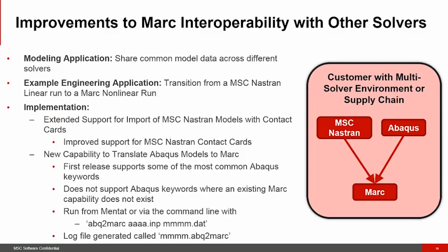You can do that by running it from Mentat or via the command line using the Abaqus to Marc input translator. Once you do that, it's a ready model that can be run. Also, a log file is generated for your reference to follow the procedure and see what happened.